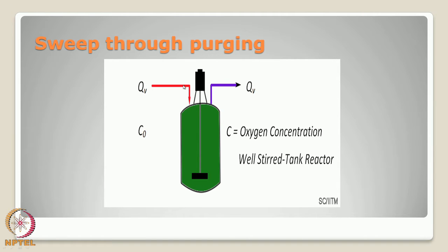Since the mixed gas should have a good mixture with the inert gas or the purge gas, we also have a constant stirrer in the tank, which continues to mix the purging gas with the mixture available inside the cylinder, so that the complete purging gas replaces the entire content.